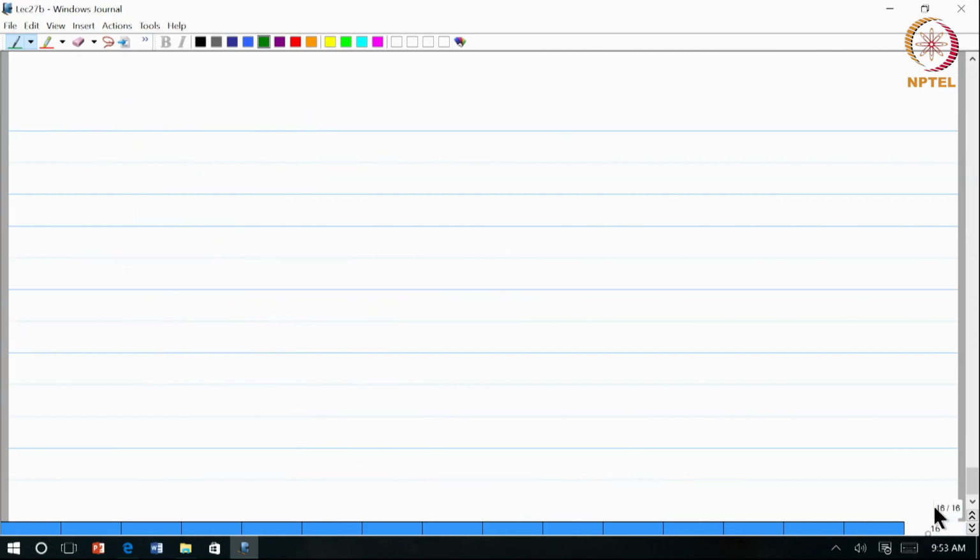Okay, so just write it down one last time. You have a 2-channel case. We are going to impose aliasing cancellation just like before. F naught of Z is equal to H1 of minus Z, F1 of Z equal to minus H naught of minus Z. The only difference is that we are now going to do a new choice for the, this is aliasing cancellation for the magnitude response.